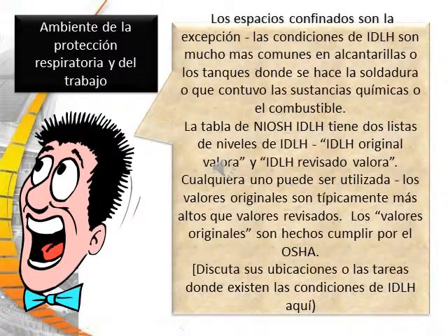The NIOSH table has two lists of IDLH levels: original IDLH values and revised IDLH values. Either one can be used. Original values are typically higher than revised values. Original values are enforced by OSHA.